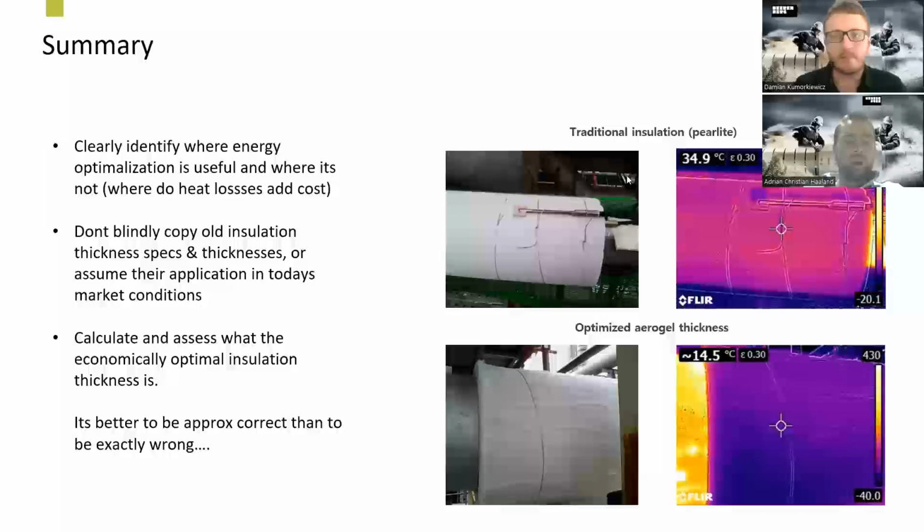Yeah, so there are some common equipment where we see large savings, and it's typically actually more so in refineries than upstream facilities, because refineries use a lot of high temperature processes. So everywhere where you see crackers, reformers, heat exchangers, large furnaces on site, that's typically the areas where insulation thickness optimization will give a very large saving compared to the investment. And it's those areas where the topic of today will save the operators the most amount of money.